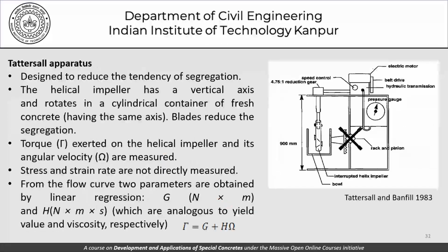As far as the Tattersall apparatus is concerned, this is designed to reduce the segregation tendencies, and we use a helical impeller and so on. I don't want to get into the details of this. This is not the purpose of this course, and the intention is only to give you a glimpse of the kind of measurements that people have carried out earlier to better understand the deformation of fresh concrete.